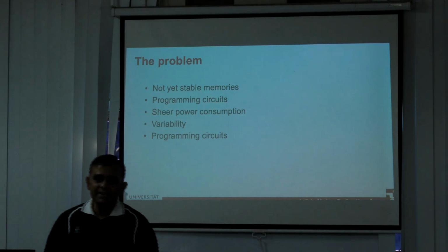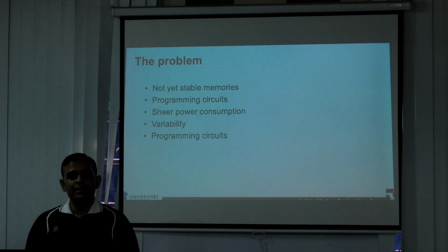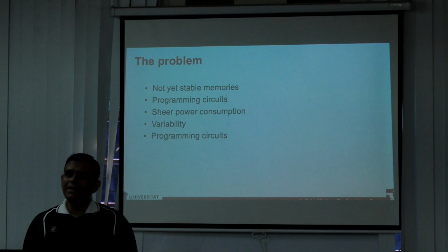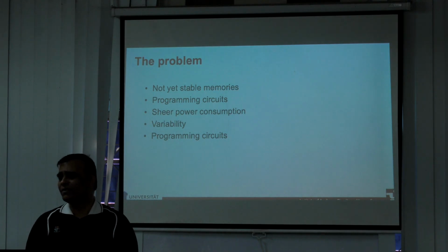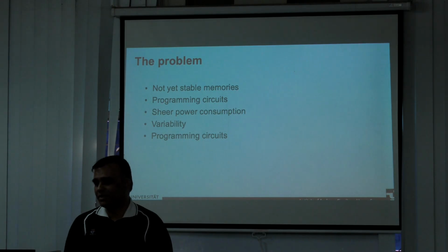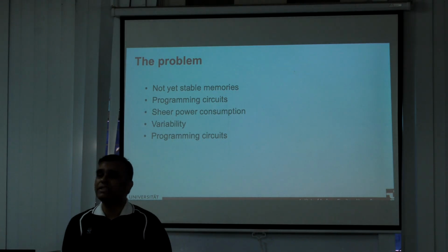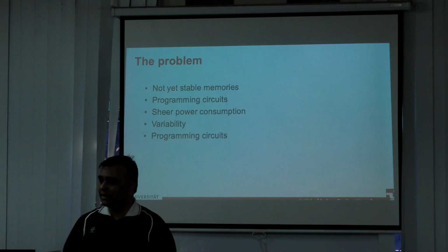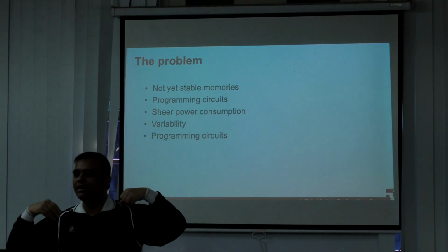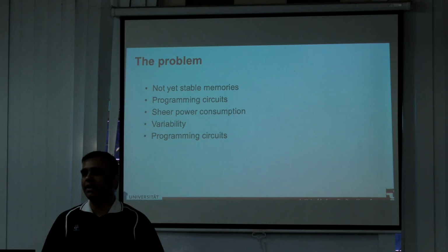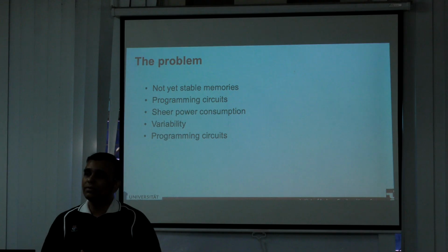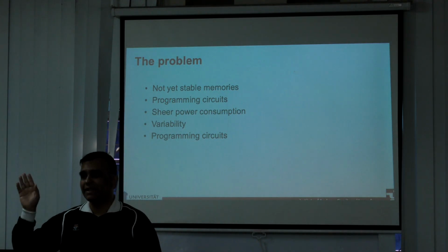The problem of power consumption is also not very solved. They say these consume less power than the equivalent digital logic, but the moment I use resistance, current will flow through the resistance, and we will have power dissipation. Remember what we are doing: we are applying voltage across a resistance, so voltage is my input. How do I reduce the power dissipation? I can increase my voltage or I can increase my resistance.